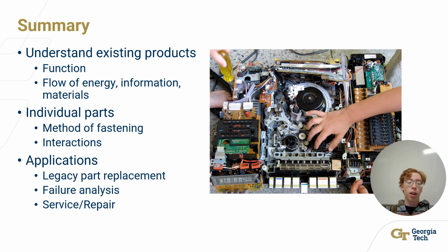They are measured and documented for possible recreation. Applications of reverse engineering include legacy part replacement, which is used when a manufacturer has discontinued a certain part. It can also be used to conduct failure analysis and figure out how to improve upon the product. Service and repair shops also use reverse engineering to understand how the product works in order to learn how to extend its life or fix it when it breaks.